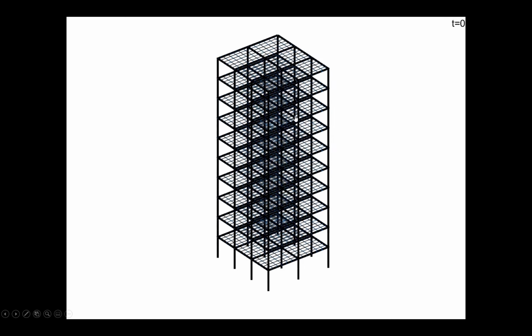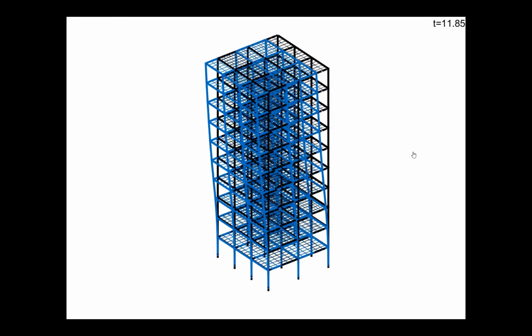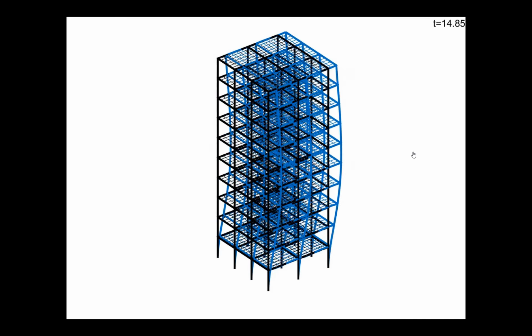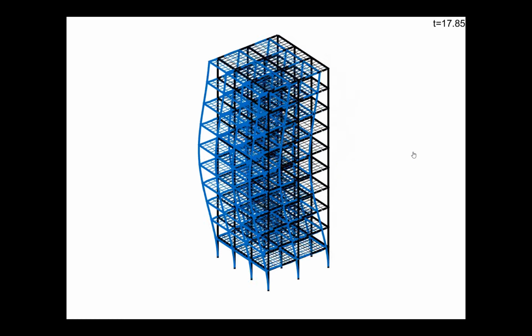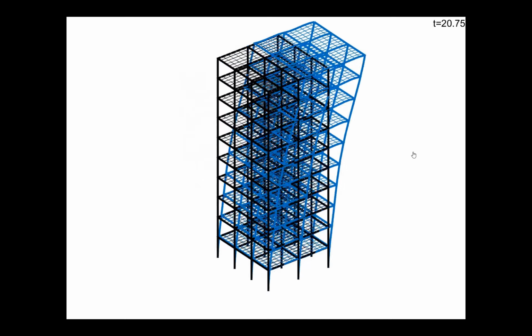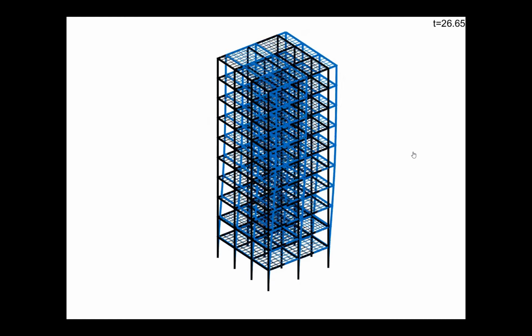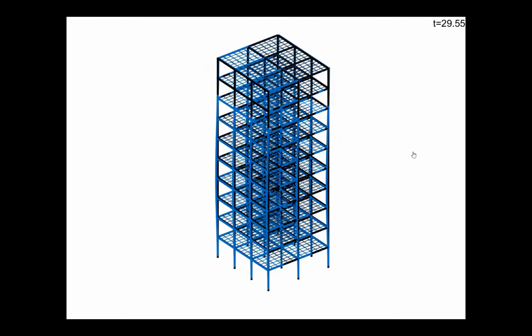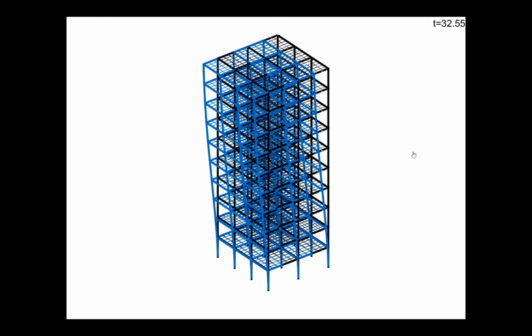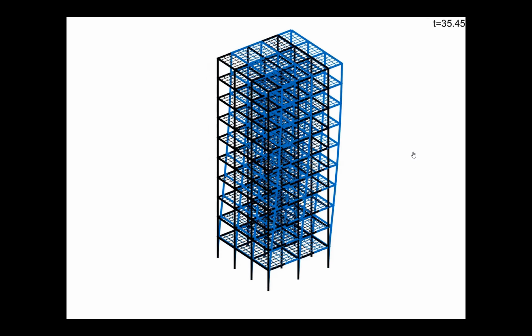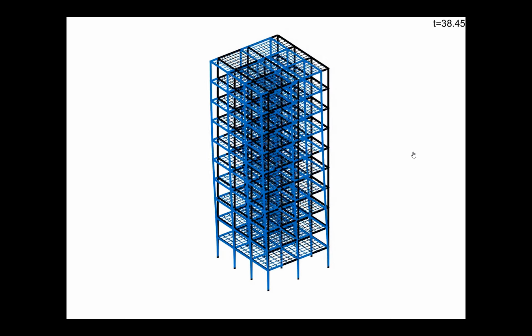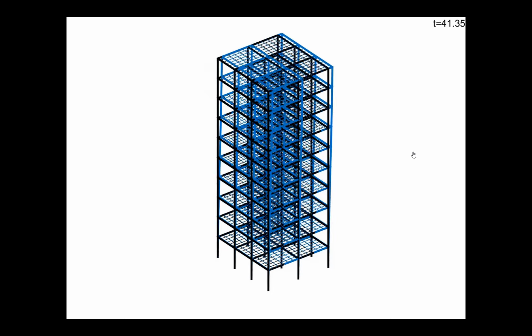This is the video of the building excited by the earthquake. The time is given here, so you will see that as soon as you reach 10 seconds, the building will start moving. Of course, the motion is much amplified here to show you exactly how it moves. It will reach a maximum displacement around 20 seconds, after which the motion will start to decay. This is the free response of the first mode, where you see that slowly the amplitude of the response decreases until it reaches rest again after the passage of the earthquake.